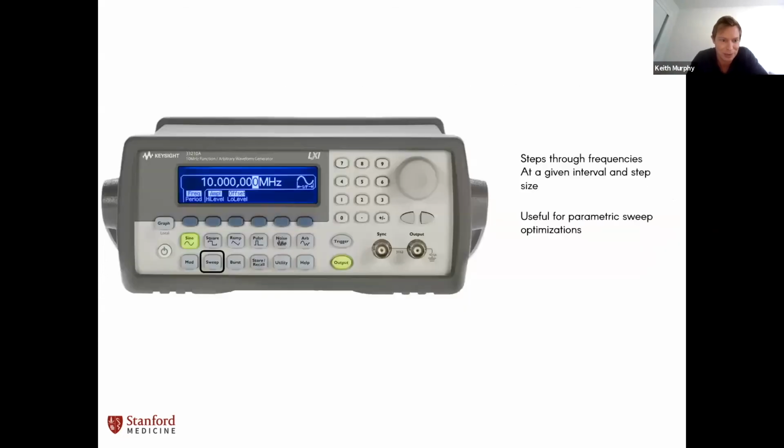We can actually jump right into frequency sweep, and then we'll go back to the other bits. So Kim is asking, what if I want to do an experiment or a test where I start at 500 kilohertz and go up to like a megahertz or something? Maybe a good example. Yeah. These boards usually have a sweep function, and within the sweep function, it'll ask you, what's your starting frequency? What's your end frequency? And then what are your steps? Do you want to step by 10 kilohertz, by 100 kilohertz, and so on?